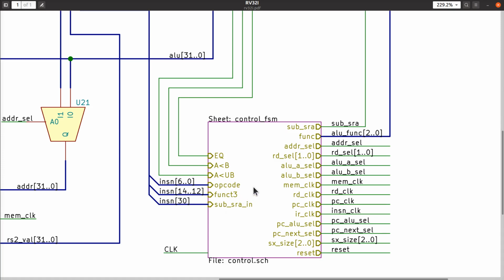It should make a certain amount of sense that what we need to do is control these clock signals here based on the current instruction that's being executed right now. For example, does the instruction have a destination register at all? Right? If it does, eventually this state machine would have to put a rising edge on the destination register clock field, for example.